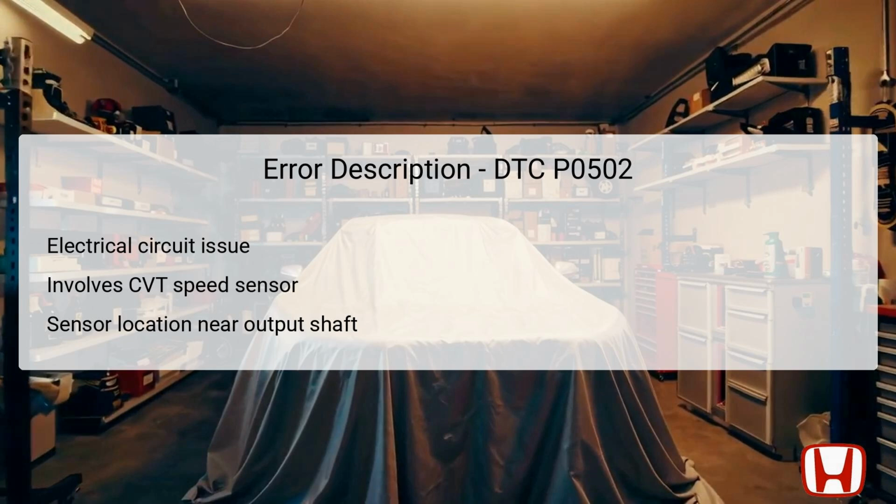Proper functioning of this sensor is crucial, as inaccuracies can lead to poor vehicle performance, idle issues, or potential engine damage. As indicated, diagnosing and fixing electrical issues is fundamental here, as mechanical problems are not the source of this DTC. Therefore, attention should be directed towards the wiring and electrical connections associated with the sensor.